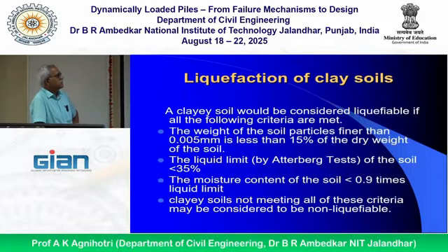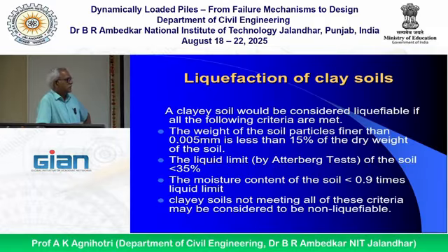Liquefaction of clay soils. Clay soils would be considered liquefiable if all the following criteria are met. Weight of soil particles finer than 0.005 mm is less than 15% of the dry weight of soil. Second, liquid limit by Atterberg tests of the soil is less than 35%.